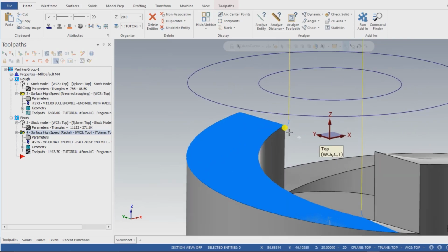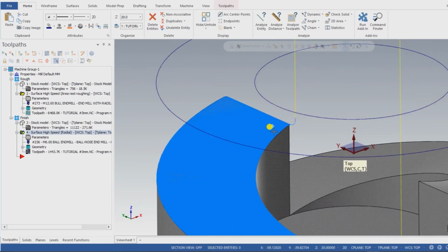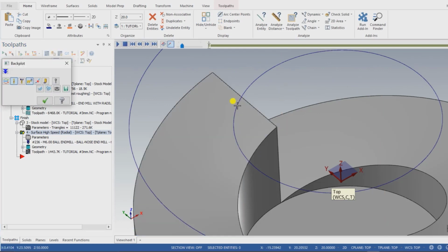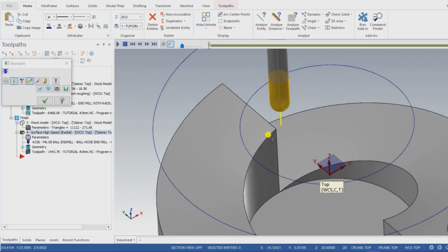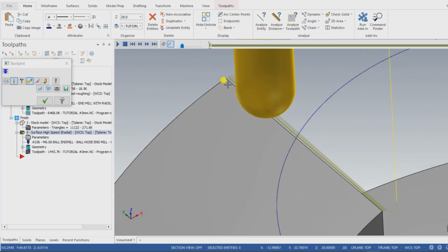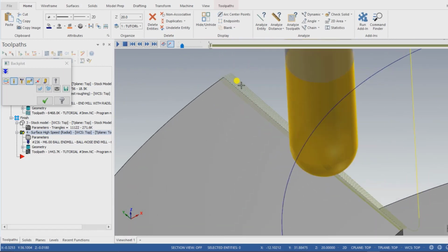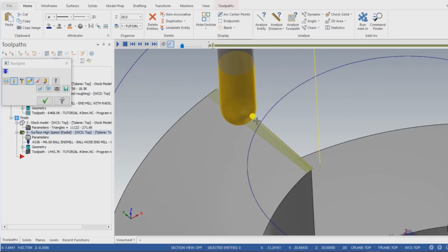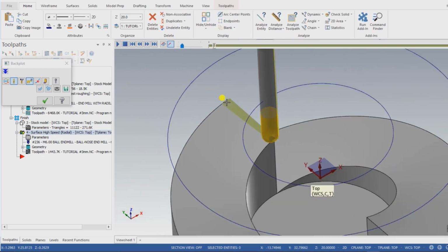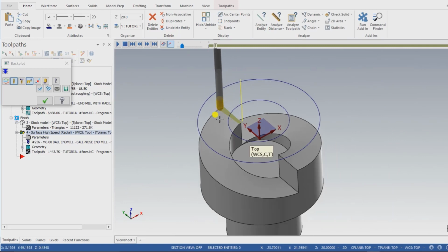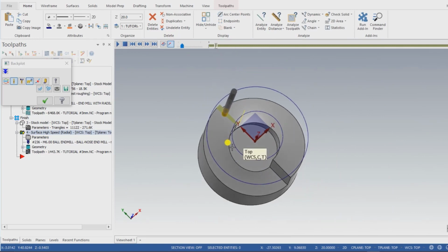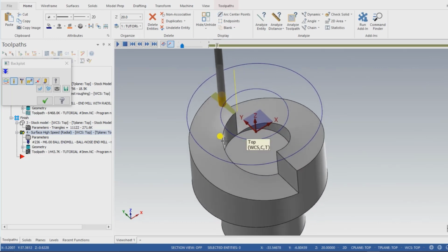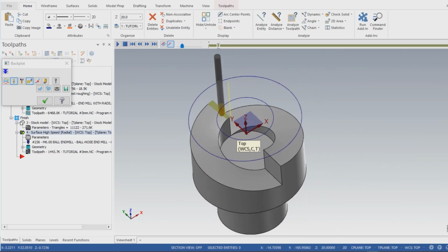As you can see, my toolpath retraction is 0. Let me show you in a 2D simulation. The toolpath comes here and automatically continues from that direction, and it cuts from here to here continuously. So guys, as you can see, my toolpath is done. And now the next step, I will show you how it cuts in 3D, or on a 3D part.